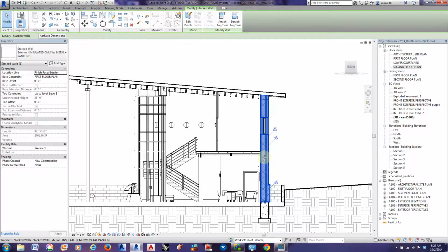So at whatever scale, if it's at a 1/8 inch scale model or a 1/16 inch model, you'd want to figure out how thick that wall is going to be. And maybe your choice is Baltic birch, 1/8 inch Baltic birch for the exterior walls. Interior walls can become chipboard, and you start using different materials for different elements in the building.